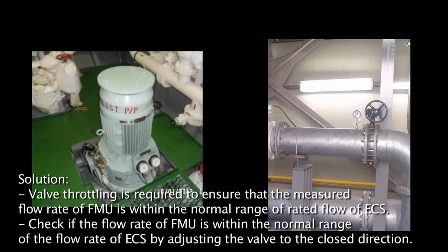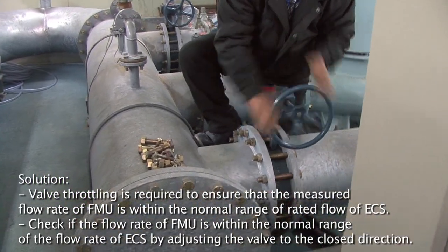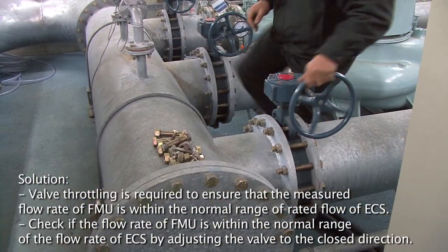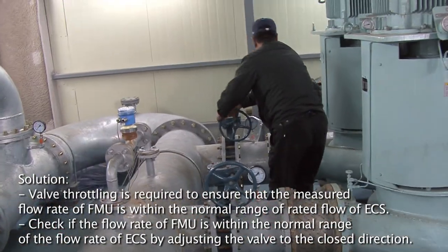Solution: Valve throttling is required to ensure that the measured flow rate of FMU is within the normal range of rated flow of ECS. Check if the flow rate of FMU is within the normal range of the flow rate of ECS by adjusting the valve to the closed direction.